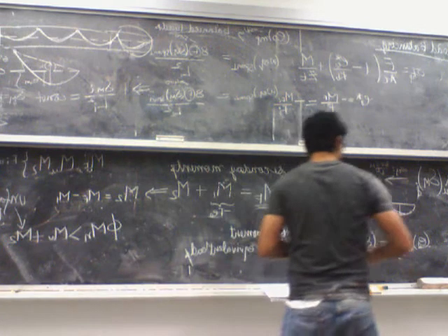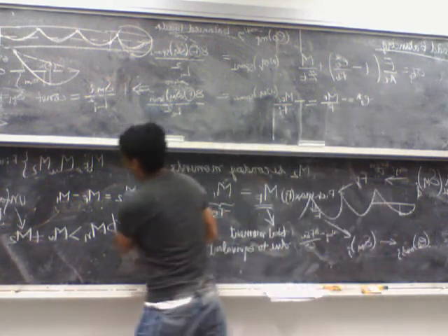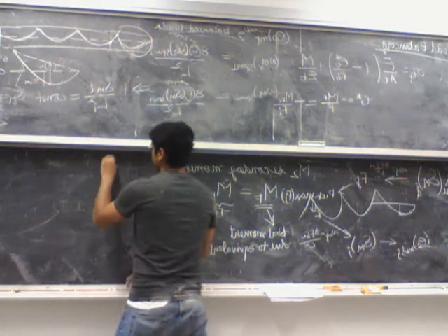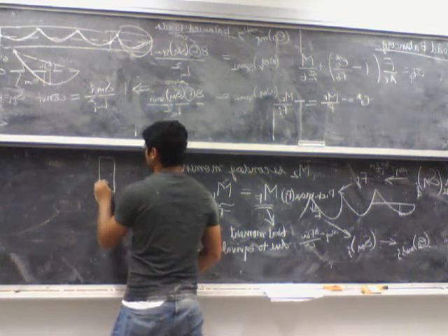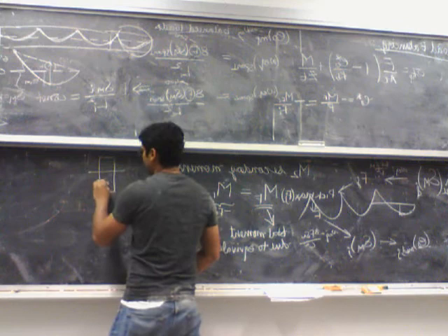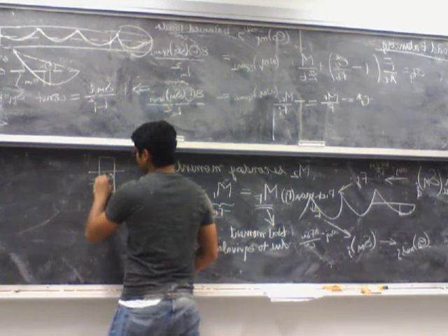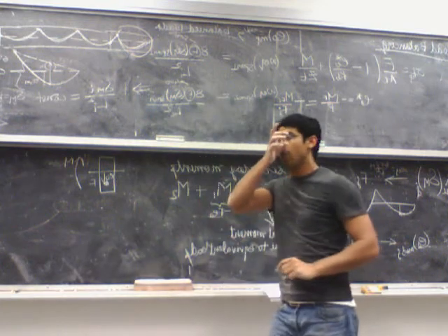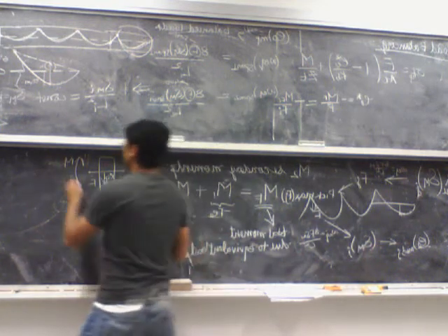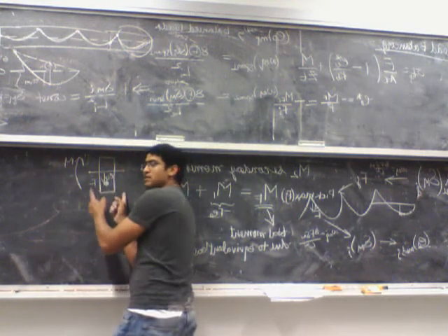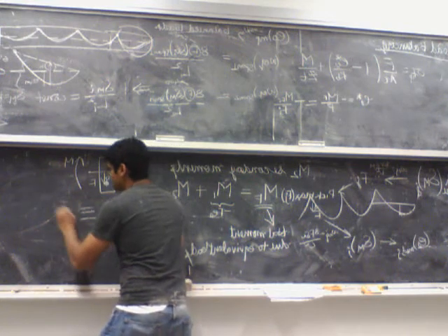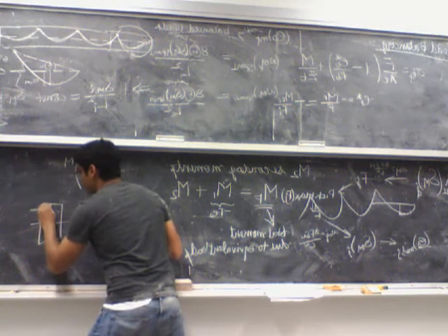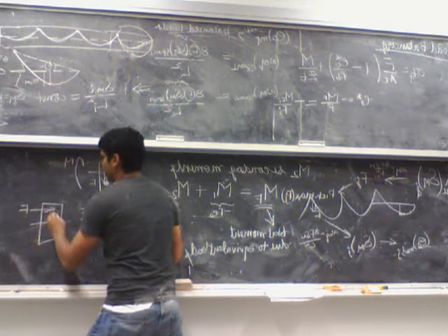So what it simply means is, normally you have a pre-stressing force F at a distance of e naught, and you have a moment of M, external moment. What the thrust line is saying is that the stresses produced in this condition are the same as the stresses produced in a different condition where the pre-stressing force is applied at a different location.